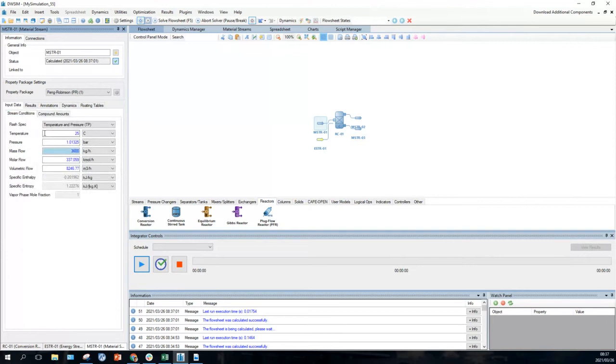So we're quite happy with the conditions. I do want to change the conditions of the reactor. So let me change the conditions. The temperature of the reactor. Oh no, it's not the temperature of the reactor, this is the temperature of the inlet stream. Sorry, right? So we leave it like that. And now we want to enter reactions. And this is where it's really important to recognize the settings on the ribbon bar on the top. Because settings, if we open that,